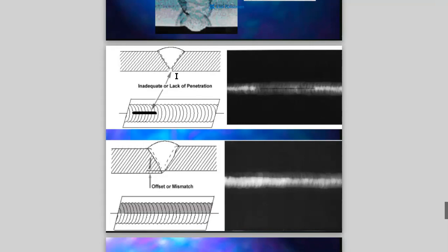And it's got to look good, can't be too drippy. And then we put cap and fill on with flux core. I did that, and that actually turned out really well the first time. I got lucky, I would think, but the preparation is really what saved me. There are no inconsistencies in the preparation. Everything was the same. It was predictable. And once you figured out how to get that weld not to fall through all the way out the bottom, you get to fall through the amount you want. All you had to do is repeat that process the whole way and just not change anything. So setup and preparation, definitely key factors.